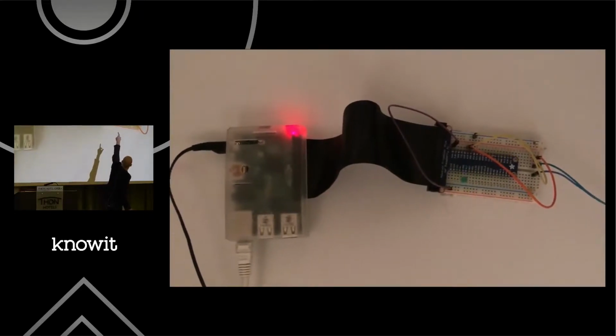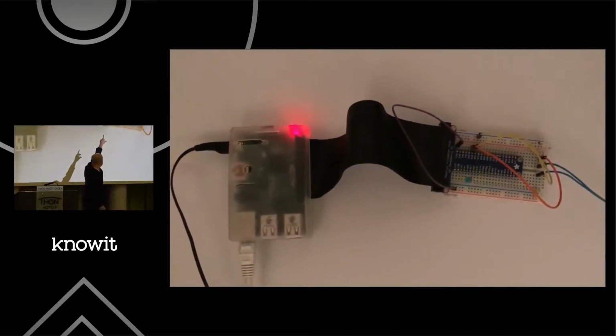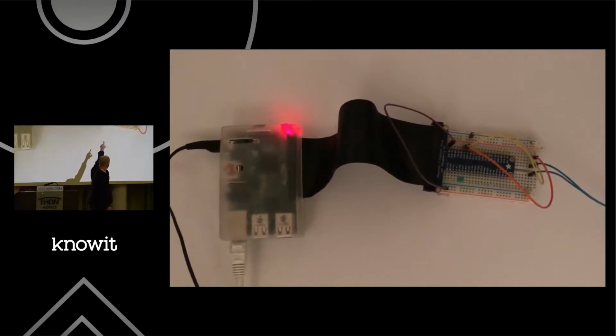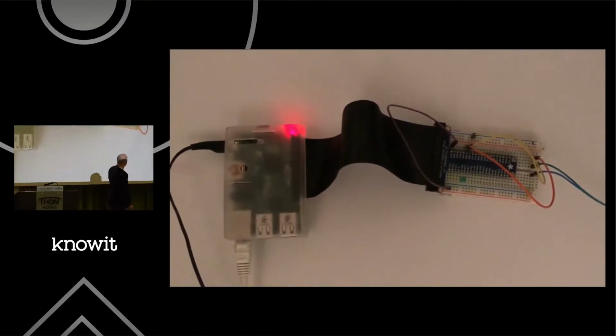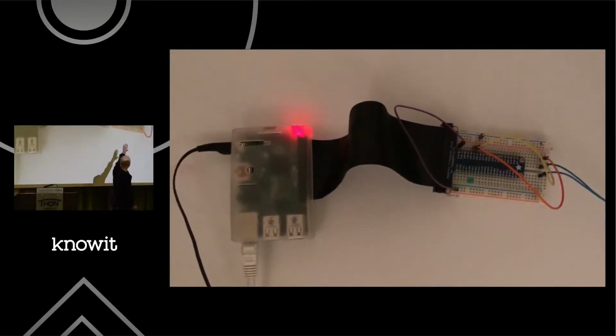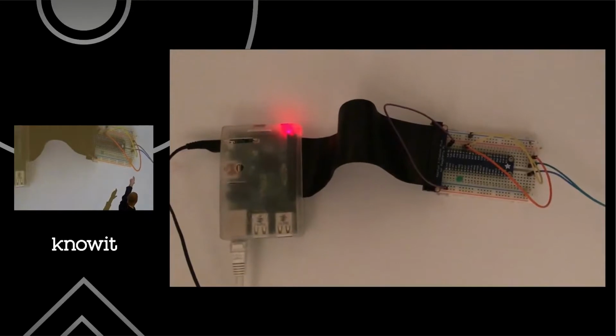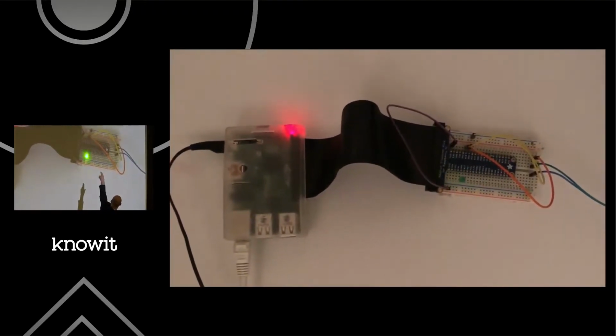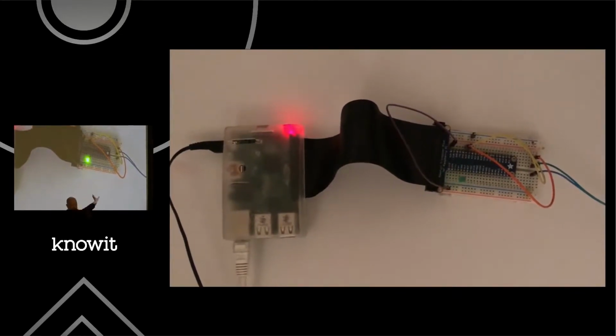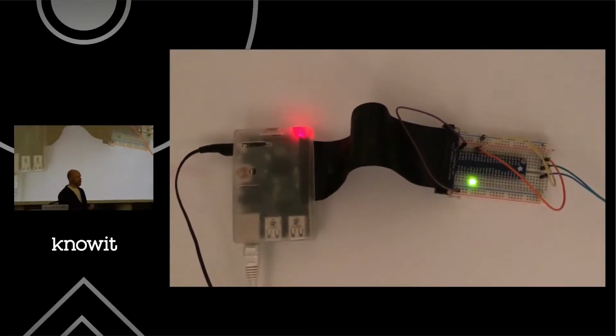So it's a really simple circuit. I take the 5 volt output from the Raspberry Pi and pipe it into the plus here. I then have a connector from the plus into the breadboard. There's a resistor there reducing the current, and then it goes up through the other side, and that goes into pin number 18, which is then read back into the Raspberry Pi.